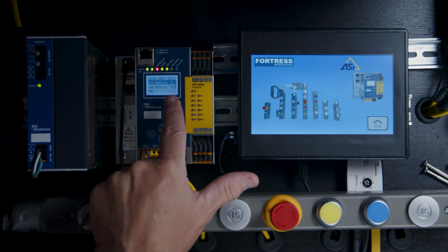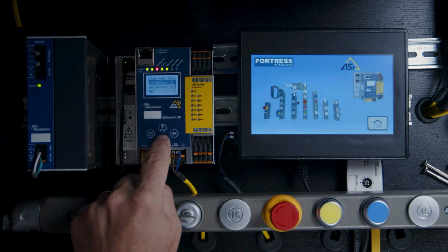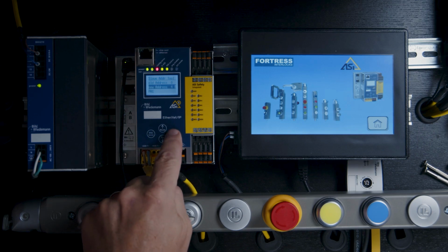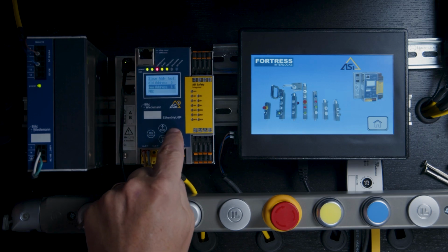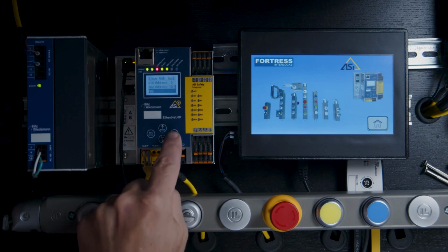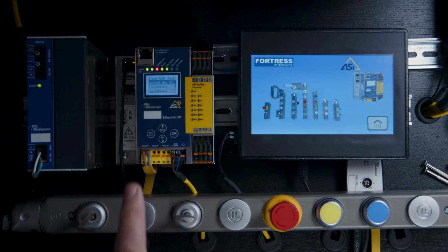Now, the old address is set at 0. So I want to leave that there because I want to change old address 0 to new address 10. Now, to get a 10 here, I need to hit the OK button until I see a 10. Okay, so I did that repeatedly. Then I'm going to arrow down to the program option and hit OK. And it tells me that that went okay. So I've successfully changed address 0 to address 10.